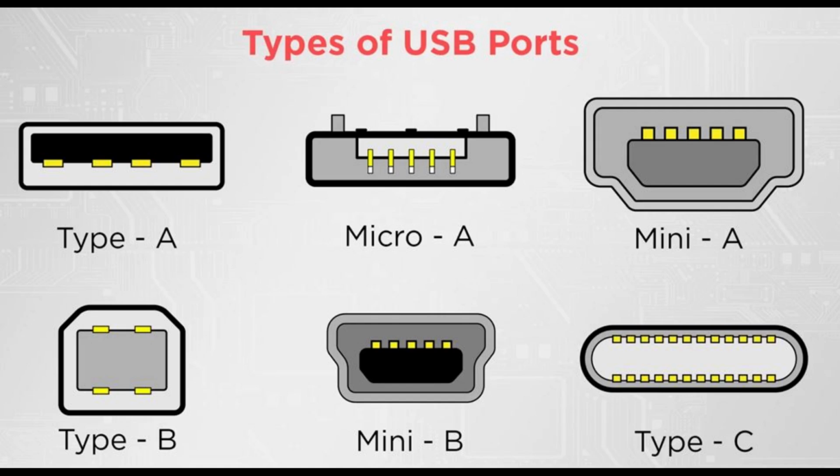From the computer user's perspective, the USB interface improves ease of use in several ways. The USB interface is self-configuring, eliminating the need for the user to adjust the device's settings for speed or data format, or configure interrupts, input/output addresses, or direct memory access channels. USB connectors are standardized at the host, so any peripheral can use most available receptacles. USB takes full advantage of the additional processing power that can be economically put into peripheral devices so that they can manage themselves. As such, USB devices often do not have user-adjustable interface settings.